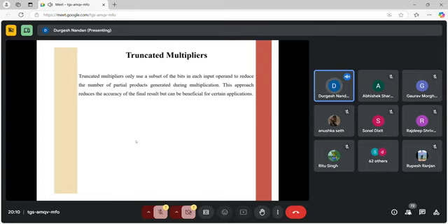But suppose we want to represent 29.000087. If we try to do that exactly, we need a 16-bit multiplier or something. That means 5-bit versus 16-bit, so roughly 8 times or more, your area, power and all those things get increased.